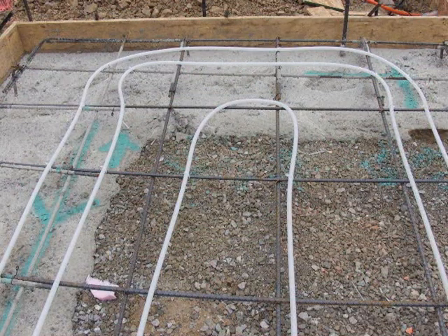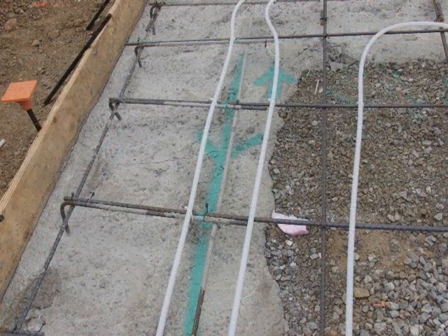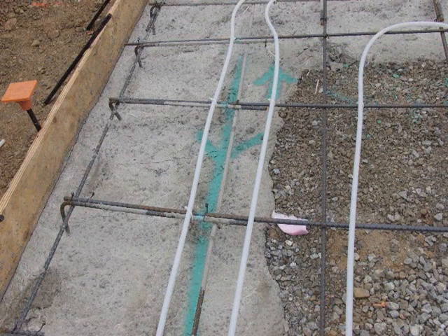and you can just attach it right to the rebar itself. Now, it's important to know where your walls are going to be when you're laying out your tubing. You don't want to have radiant tubing directly underneath the wall. The risk of that is that you might actually shoot a nail when attaching the wall to the concrete down into the radiant tubing. So we use paint to delineate where our walls will be so we can run our tubes and know where to stop them. Like you can see here, we've turned our curve before we get to that green so that we know when we shoot our wall down we won't hit that pipe and damage the tubing in any way.